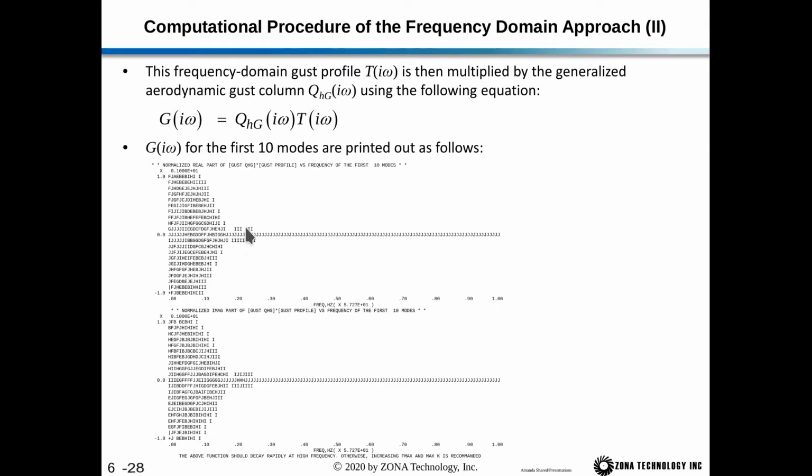So you want the Gust to decay out to about 0, so that since we're chopping off everything greater than 57.27 hertz to infinity, this should all be 0 because we're chopping it off and we're not including it in the integration. So if it's not decayed out to 0, then obviously you're chopping off important signal here that's non-zero. But since it does decay down to 0, everything that we're chopping off greater than 57 Hertz is practically zero, so we can ignore it when we integrate back from the frequency domain to the time domain. And that's the purpose of this note here.